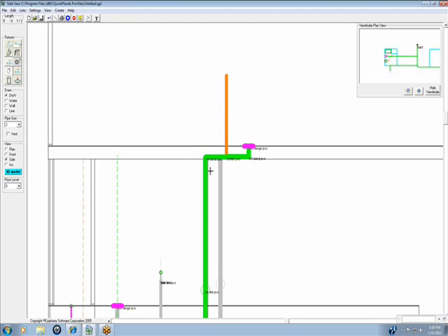But does your code, Mr. James, does it allow any wet venting at all? Yes, only on the same floor. Okay. Yeah, our code is the same way, same floor as far as that goes. Yeah, no, we could do that. So we could tie a lav into that vent if we needed. Right. How about a horizontal wet vent? No. Does your code allow that? No, only vertical. Okay, gotcha. So you could put a lavatory right there.